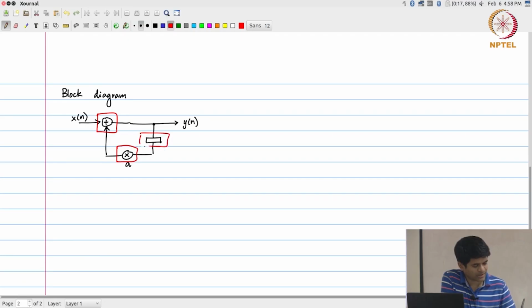These are functional blocks, and we have the wires that are essentially drawn as circuit level connections between them, right. So you can instantly recognize that this is very close to a hardware representation. This is directly saying this is how the hardware will look. If I had these blocks, a register, a multiplier, an adder and so on, I could directly implement this in hardware by wiring this up together on a circuit board. Okay. What would the FIR filter look like for this?